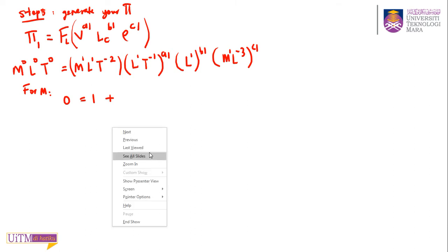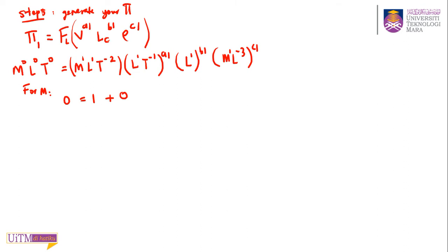Slowly. Okay, in this equation for F L, you have M equal to 1, so that is M 1. In V you don't have any M, so this will be plus 0, and in L you also don't have any M, so this will be plus 0. In rho you have 1 M, M1, and this will be power C1. Okay, this is just to denote. Why do we write this? Because we want to find the power of that pi, what power it is.